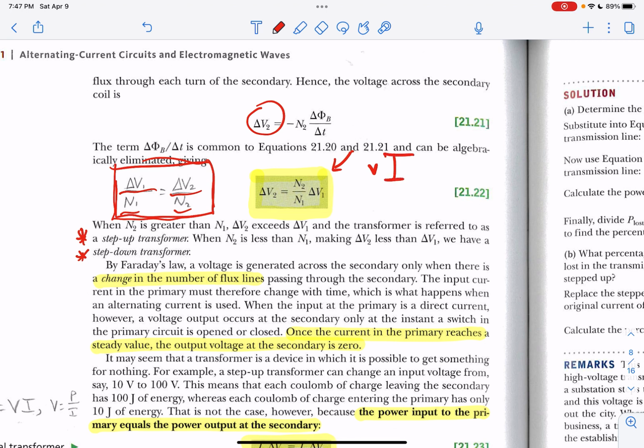Now, if we were to immediately send that current, that electricity, through the wires at this super high current, all of that current plowing through the wire would produce a tremendous amount of heat, and there would be a tremendous amount of electrical energy loss. So what they do right outside the power plant is a huge area, sometimes several acres in size, filled with transformers.